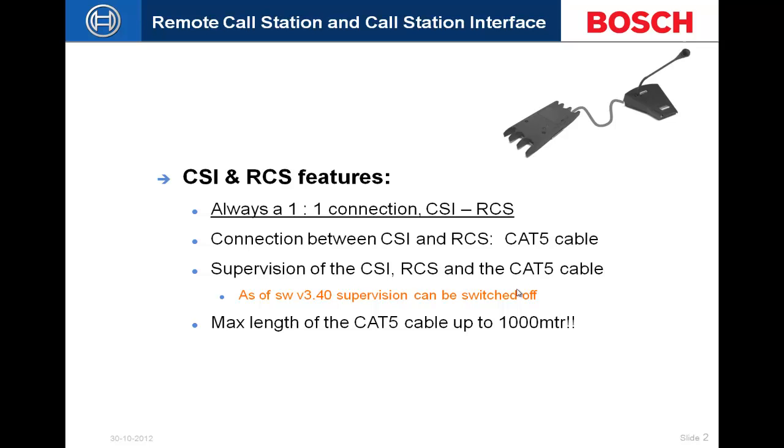At that point, I recommend probably remote powering the system, and this does not, I repeat, does not account towards our fiber length when it comes down to how many nodes versus our system bus length. If you've watched the network topology video, we essentially go over our amount of fiber we can have in the system versus how many nodes we have in the system.